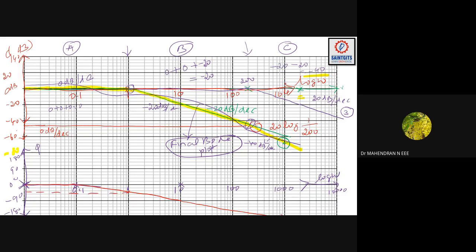Measuring the degree at this point, it is crossing the corner frequency at 1, and the corresponding degree is minus 45 degree. Then the change in slope will be minus 45 degree per decade through the line. So this is the second term, and this is your first term.